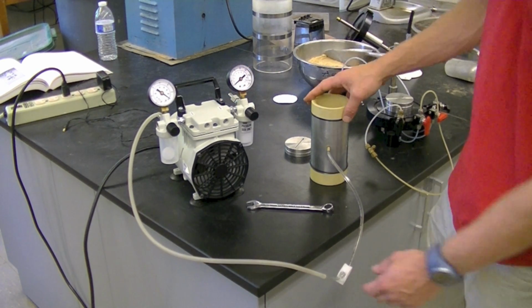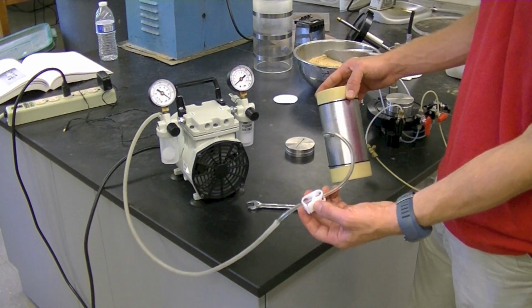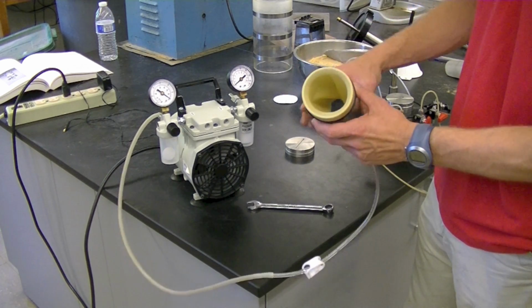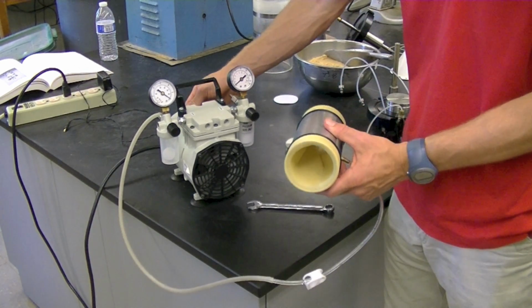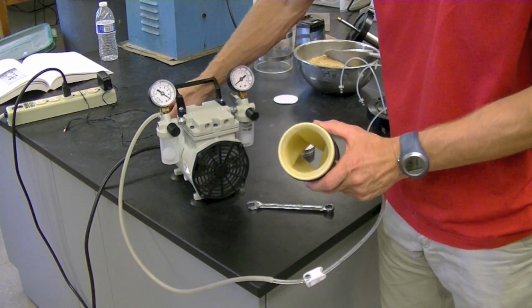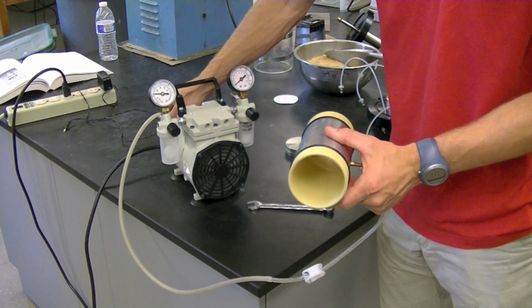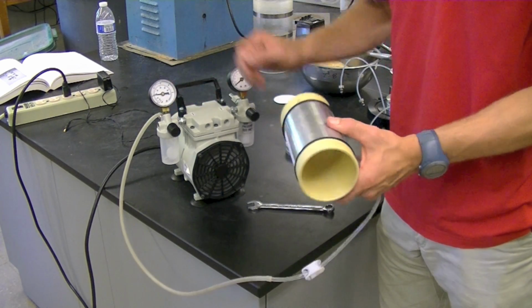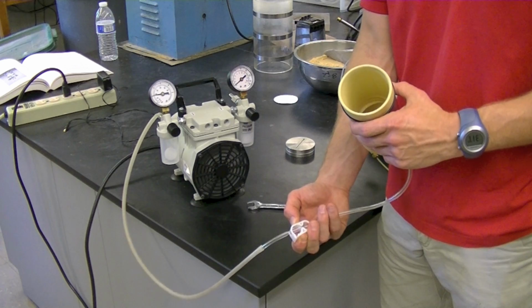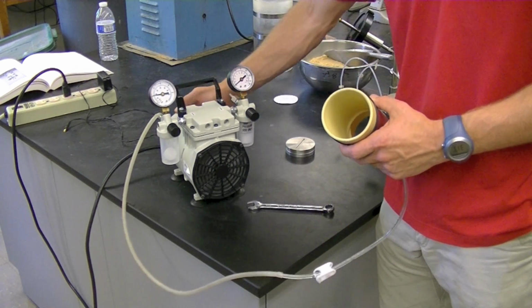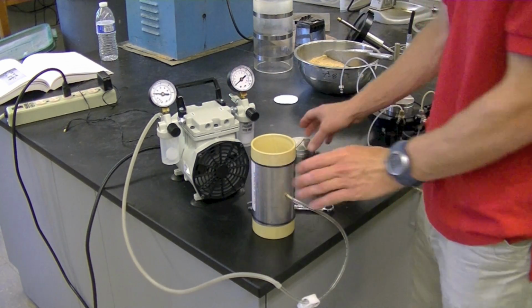Triaxial mold with a tube stem is needed. A bladder cylinder or rubber membrane fits inside the mold, holding the specimen in once the mold is removed. A vacuum must attach to the tube stem to remove air from the outer diameter of the rubber membrane and the inner diameter of the mold. A plastic pinch is attached to the tube stem to close off the vacuum when necessary.